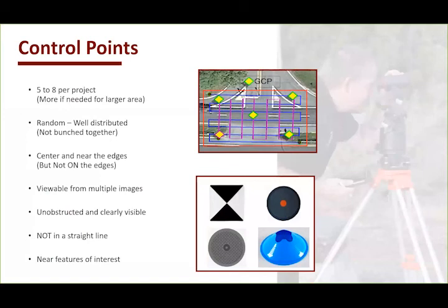You'll see that the XY, when you get very good overlap in your nadir images, so your two-dimensional scale diagrams are coming in extremely well, that Z many times is what falls a little bit behind. If you're looking to work in a 3D environment where you're looking to harvest 3D data points from a point cloud, those are times where you may need to introduce ground control points.